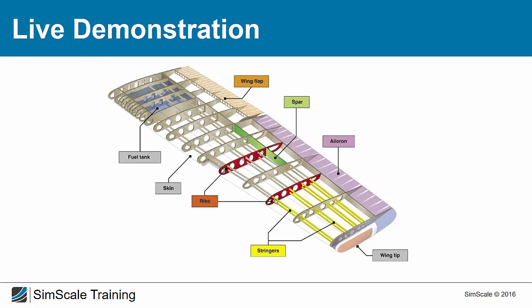And this creates a very strong structure, which is in theory very effective against bending and torsional load. In the end, you're putting just a metal skin on this structure, and this skin is then the shape of your airfoil. A big advantage of this design is it's not only very light and stiff, it also leaves a lot of additional space, for example, where you can integrate the fuel tank. As I know, in most commercial airplanes, you will find the main fuel tanks in the wings.